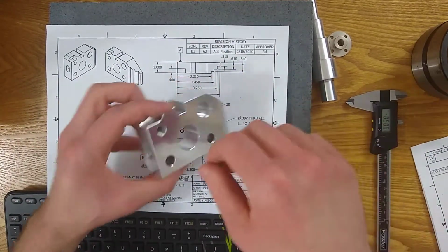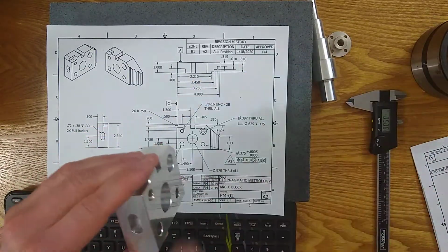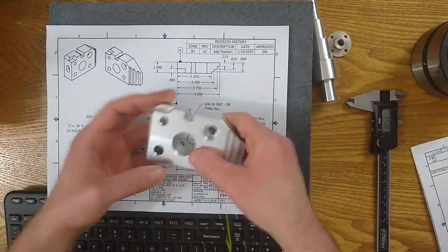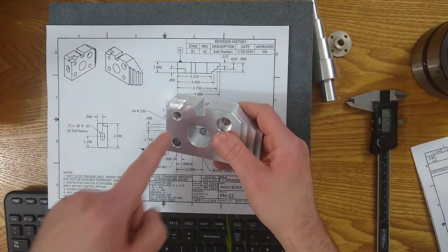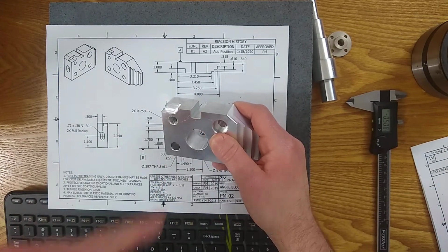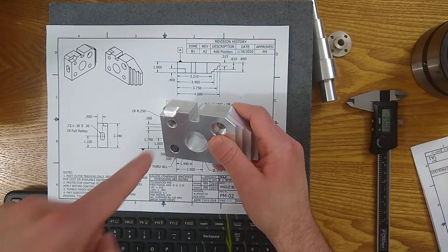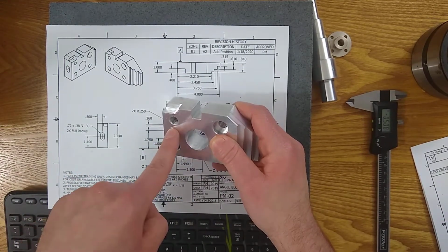So another thing to do when you're checking the hole is, it'll go in, but how loose is it? How much can you move it around? I've seen it happen. If you do the opposite, let's say we drill for a cut tap and then we try to tap with the roll tap, it's going to break. It's going to interfere.